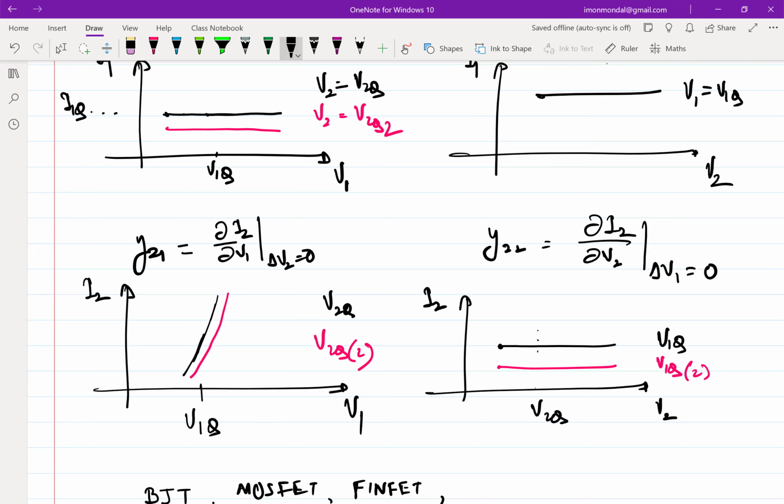Okay. Very good question. So he's saying the graph of the function should pass through the origin. Why do you say so? Right. So it's y equal to mx, a linear relationship, in which domain? In the total IV domain or in the incremental domain? This is not an incremental domain. So when you say it should pass through the origin in the incremental domain, there is a lot of assumption going into it. First is the linear domain, but there is also a shift of axis.